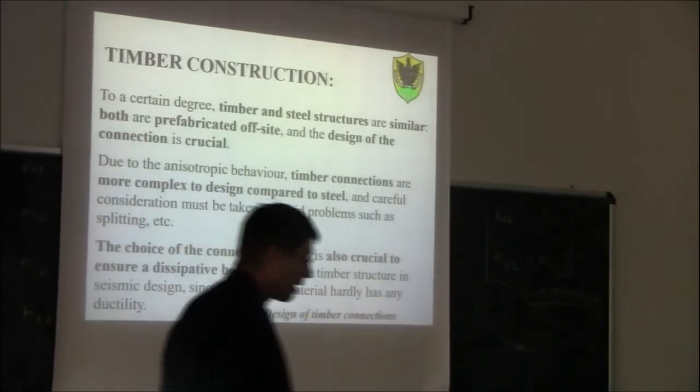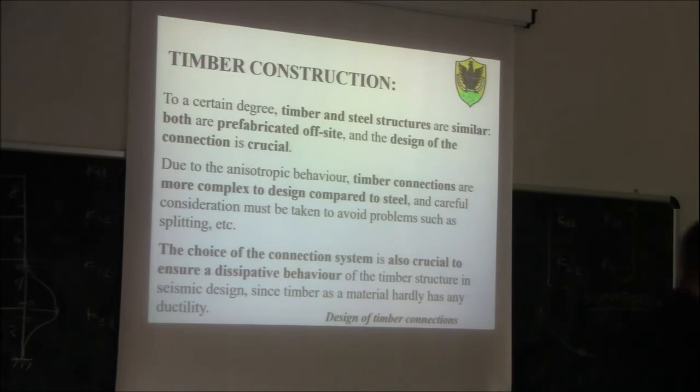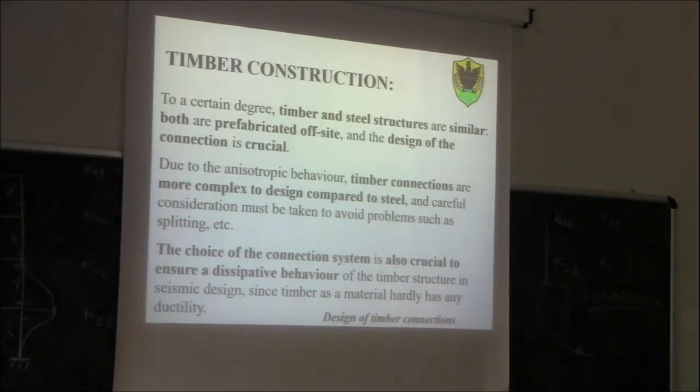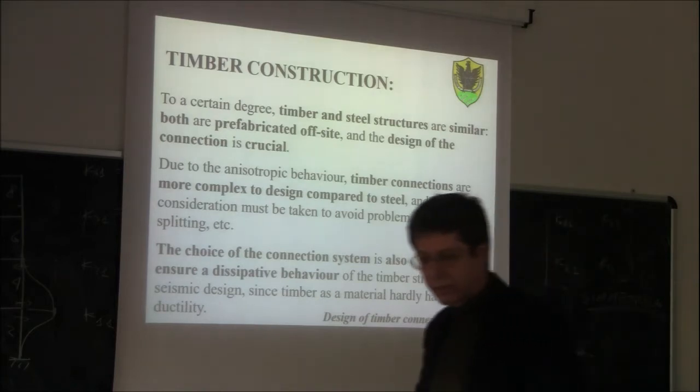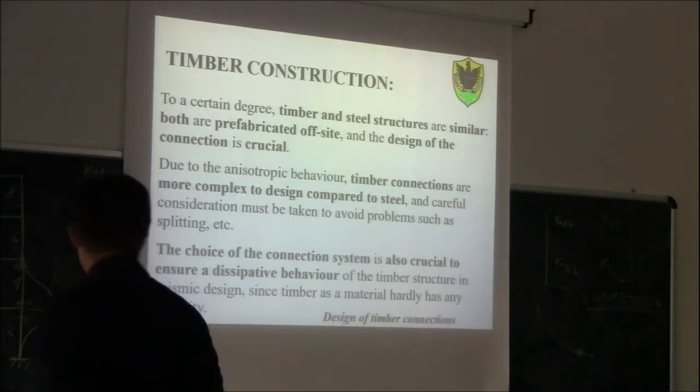We also have to keep in mind that if we want to design a dissipative structure, the only way we can get some energy dissipation into a timber structure is basically to make sure that the connectors, so nails, screws, dowels, bolts and so on, will plasticize.